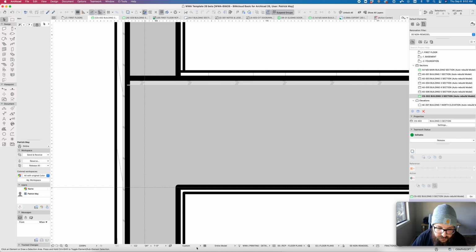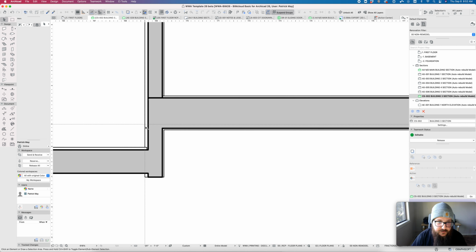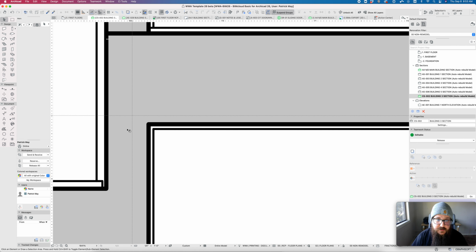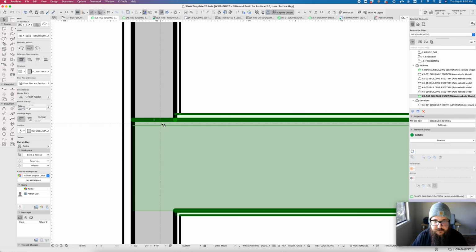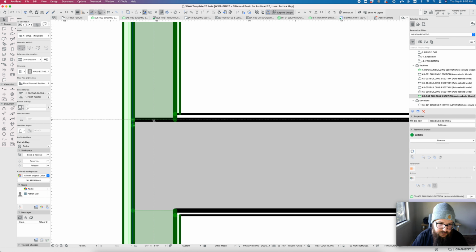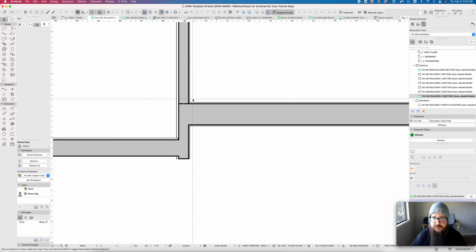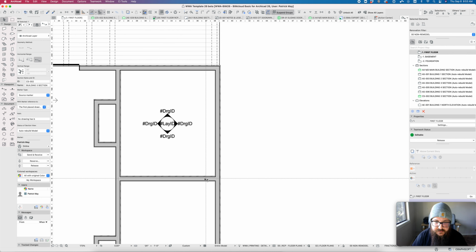And when we look at this with the documents pen set, we can see that we get that nice clean, the white fills, cut fills for the siding and sheathing, and then the ceiling board and the wall board all clean up nicely. The wall to floor framing cleans up nicely. We do get a line where that subfloor comes through because this building material is different from this building material, and it's going to create that separation. But we really want this graphically to be as close to our floor plan graphics as possible, where we are showing all of these walls cleaning up nice and evenly.